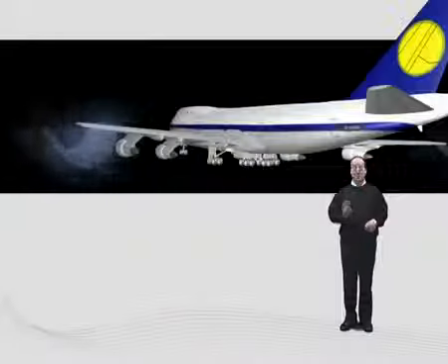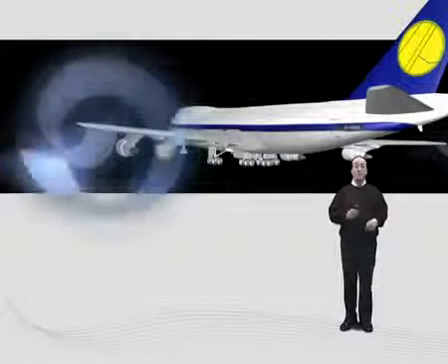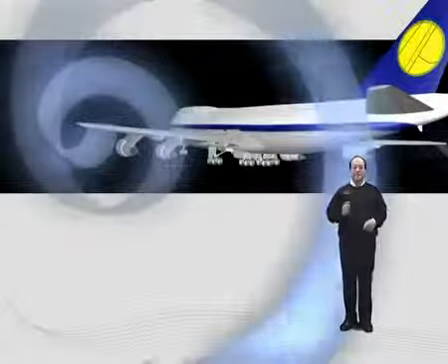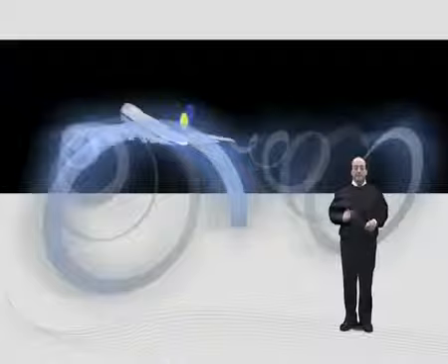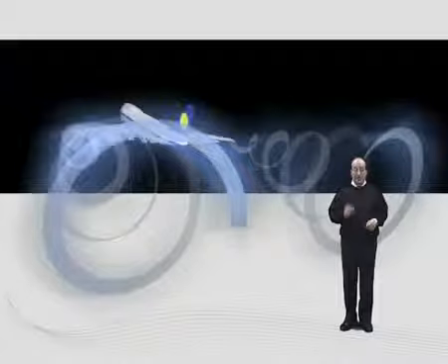The vortex wake strongly interacts with the lift distribution along the wing because it influences the so-called downwash, which is the mass of the air that the wing pushes downward. For these reasons, also the induced drag is influenced by the vortex wake.